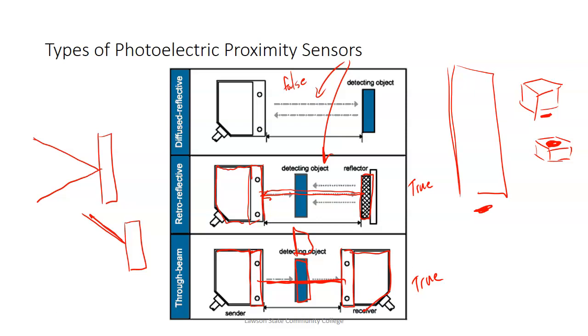So if you drop those that have that RFID tag on there, if you put the tag down, it'll say there's nothing in there. It says there's nothing in the magazine. So these guys are very reliable, but they're electronic, so they're either going to be 3-wire sensors or they're going to be 4-wire sensors. And we'll talk about that in a minute.